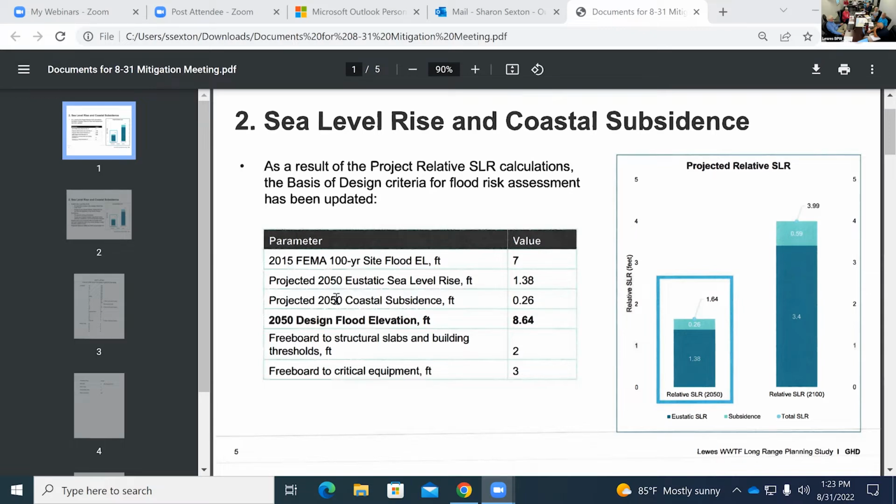That's also kind of following Maryland's Chesapeake resilient building model. They're using 3 feet for any critical infrastructure that has a public component to it over $500,000. So basically, anything that you're constructing that's a public facility, municipal building, they're doing the 3 feet of freeboard above the base flood elevation. All right, well, if that's acceptable to everybody, then we'll pass that on to the board.